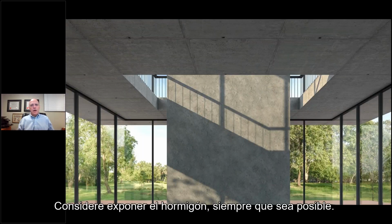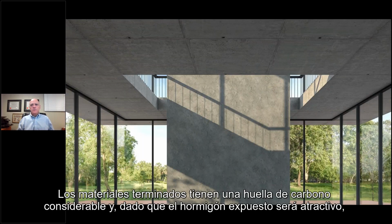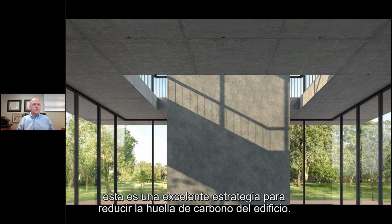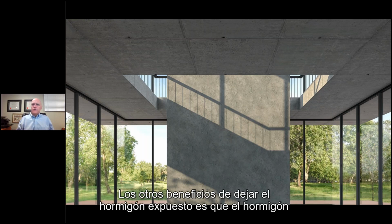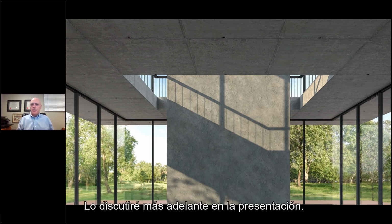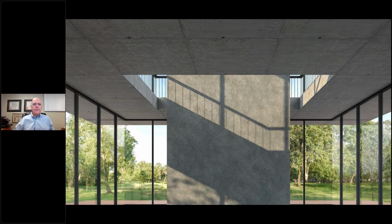Consider exposing concrete wherever possible. Finished materials have a considerable carbon footprint, and since exposed concrete can be attractive and is fire resistant without the need for additional protection, this is an excellent strategy for reducing the carbon footprint of the building. The other benefit of leaving concrete exposed is that concrete absorbs carbon over time through a process called carbonation, and I'll discuss that later in the presentation.